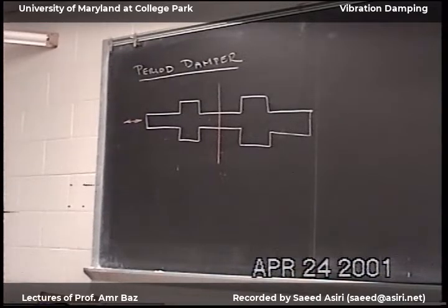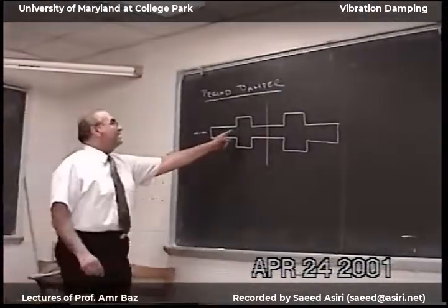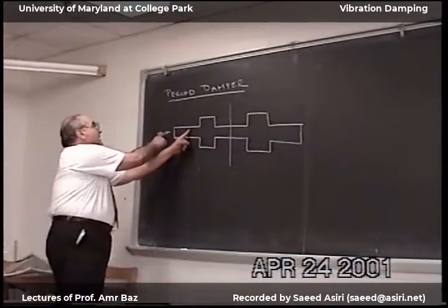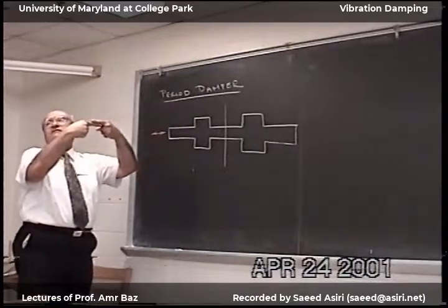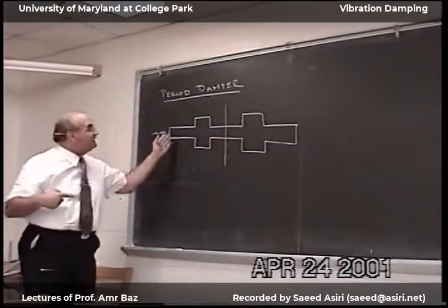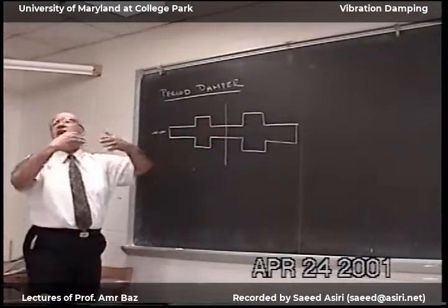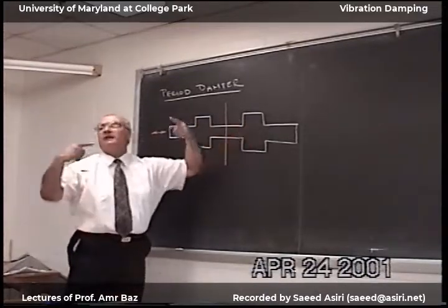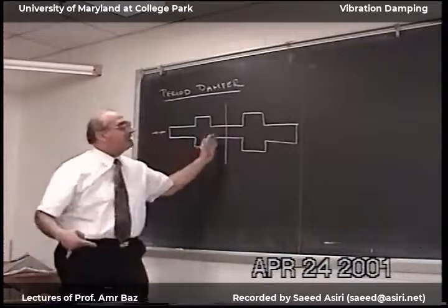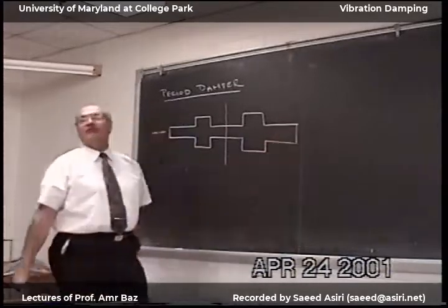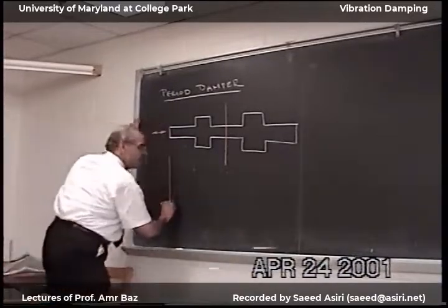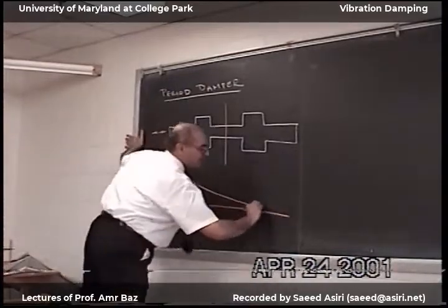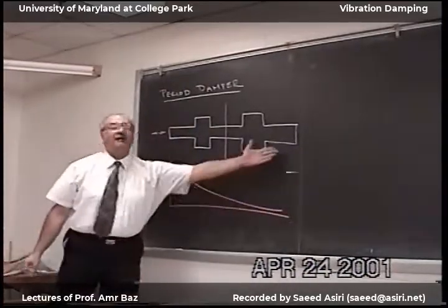Then I have reflection and I have transmission. If I design it properly, I can make this reflection come with the incident wave and do destructive interference. Then I can reduce the amount of transmitted wave. If I design it properly, at each one of these steps I'll have this destructive interference. At the end, I have very low transmission of energy. The bottom line is, I have very high amplitude here, and then at the end, I have very low.